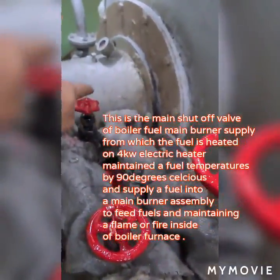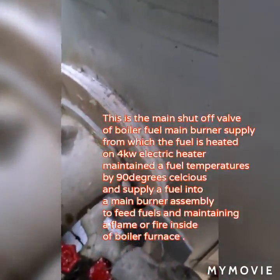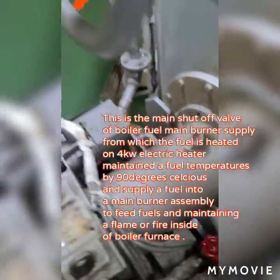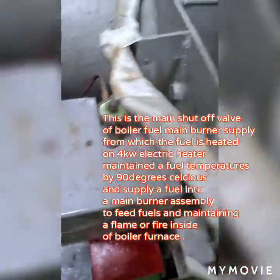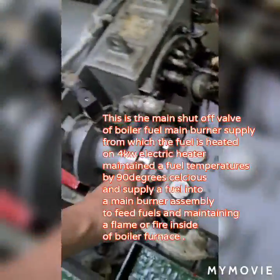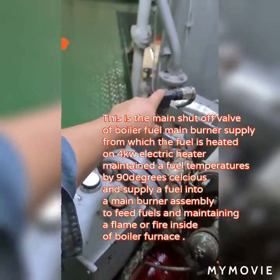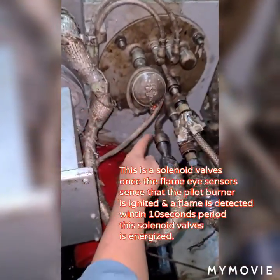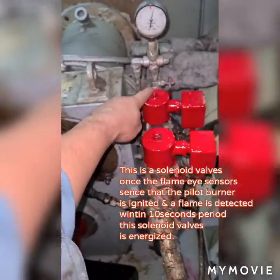This is the main valve shut-off of the boiler fuel main burner supply, from which the fuel is heated by a 4 kilowatt electric heater, maintaining a fuel temperature of 90 degrees Celsius, and supplying fuel to feed and maintain a flame or fire inside of the boiler. This is my fuel going into my main burner assembly.